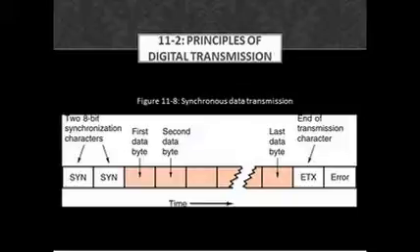Each block of data can represent hundreds or even thousands of 8-bit characters. At the beginning of each block is a unique series of bits that identifies the beginning of the block. Two 8-bit synchronous, or SYN, codes signal the start of the transmission. Once the receiving equipment finds these characters, it begins to receive continuous data: the block of sequential 8-bit words.